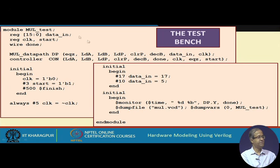Now, the test bench. We have written a very simple test bench to verify our design. So, you see what we have done. We called it multest. Data in is coming from outside, so this will be generated by the test bench. Somewhere we have initialized data in, clock and start, and done is the output signal. So, we have instantiated the data path and the controller with all the signals as specified, right. In the initial block we are just initializing the clock to 0, and in this always block we are generating a continuous clock with a delay of 5, clock equal to not clock.